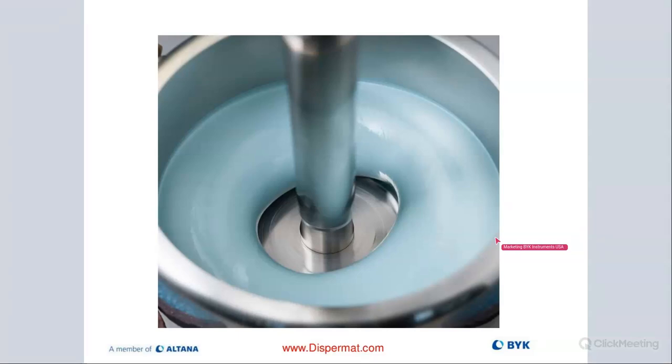Of course, if your viscosity is lower, almost like water, or like 500 centipoise or less, it will be more difficult to actually achieve the donut, because the donut would immediately collapse as soon as it's being formed, because there's just not enough viscosity.